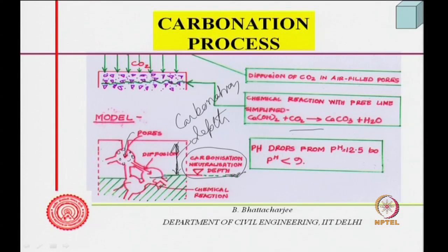Now, if it is fully submerged concrete, moisture will be available, but the carbon dioxide concentration will be very low in dissolved water. And if it is fully dry concrete, the reaction will not proceed, although carbon dioxide is there. So, this occurs only at a certain relative humidity.